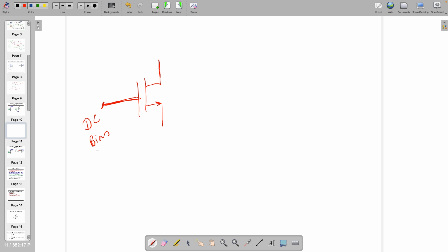Sir, to drive the MOSFET so that we can amplify in the saturation region. Sir, with DC we can get the operating point where we can superimpose small signals so that it can be in that amplifying region. So what is bias? Bias is a driving DC voltage.